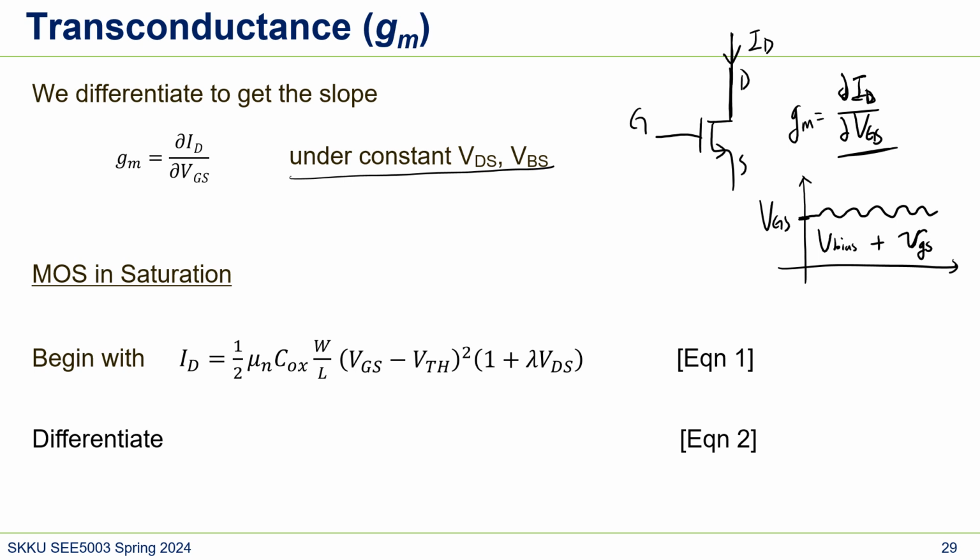This is important because usually this input goes to the gate. Usually, not always, but usually the input voltage goes to the gate, and then the output is represented by a function of current. So if we apply an input, then how much does the output current change? Here's some math, and I think this is really important math. I still use this differentiation quite often when designing circuits.